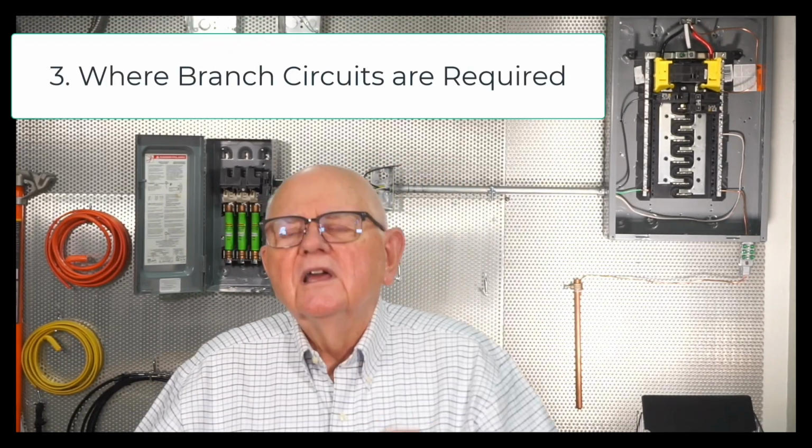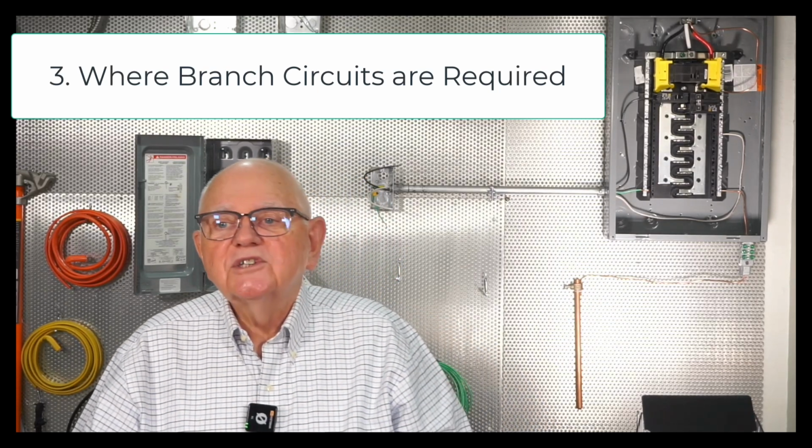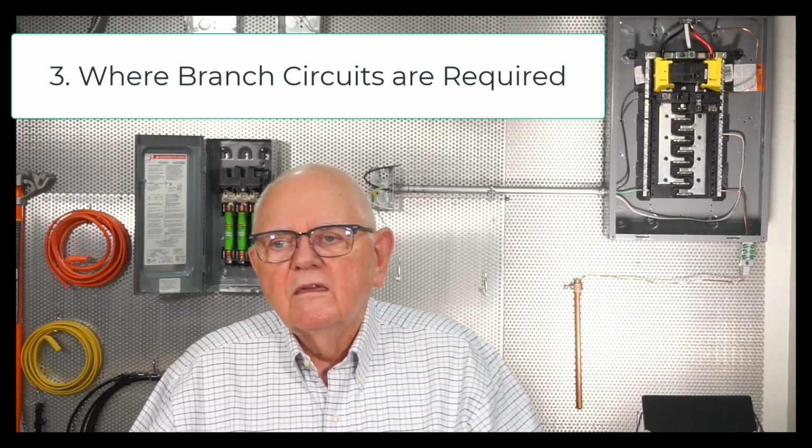Subsection C in 210.12 covers dormitory units and where we have to have AFCI protection in dormitory units. Because remember, we're preventing fires. We certainly want to prevent fires in dwelling units. We want to prevent fires where people are sleeping in dormitory units. Section D talks about other occupancies, 210.12(D): hotels, patient sleeping rooms, sleeping quarters, fire stations, police departments, or whatever. So they have to have AFCI protection. Let's move into Section 3 now, where we talk about where branch circuits are required.